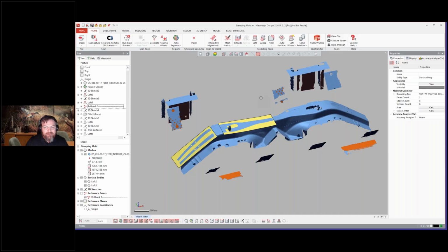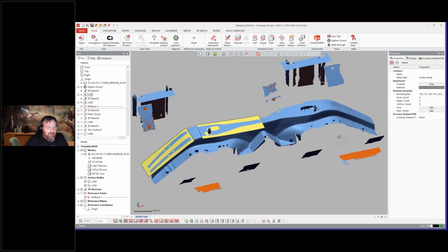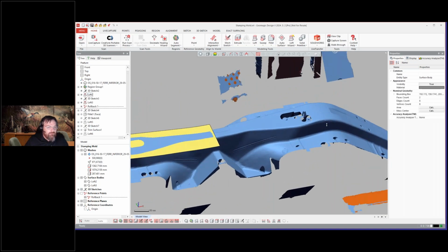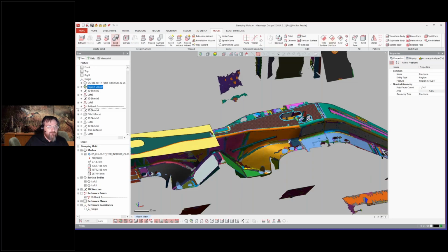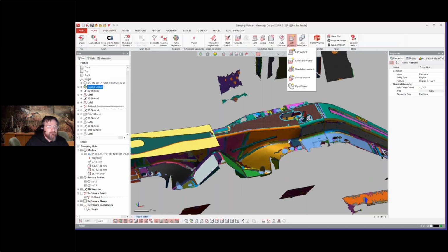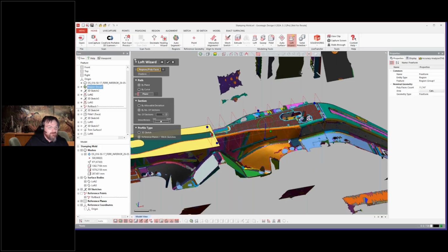And this is one side effect that's a benefit from history-based CAD modelers that's really nice, being able to do this. So you see here that we did a couple different lofts on the surface, and those lofts were generated not just by creating a loft manually like you would inside of a CAD software, but you actually can come in and I can select a region like this. I can come over to our wizards and I can say loft wizard.